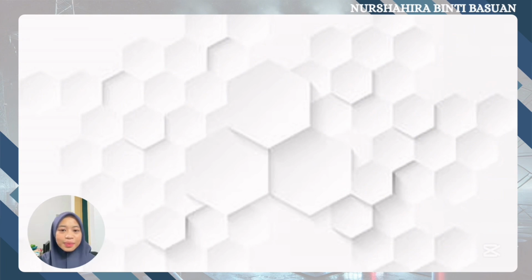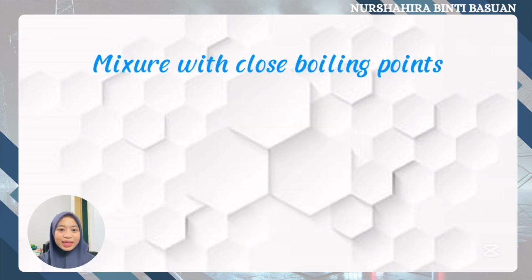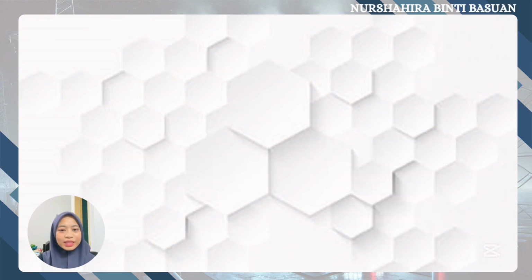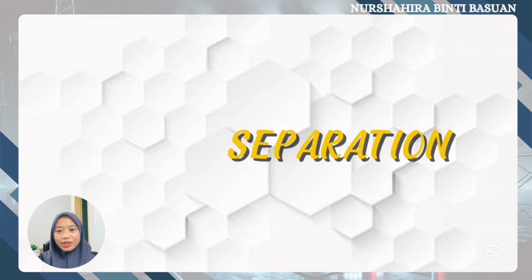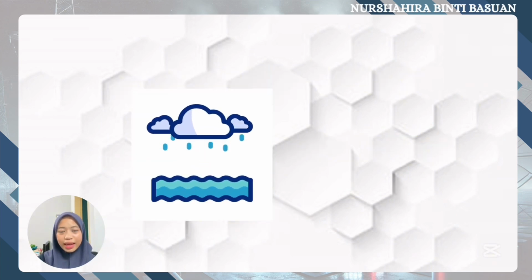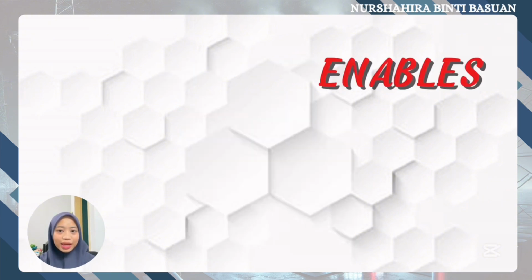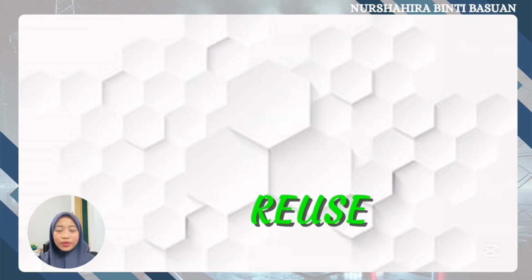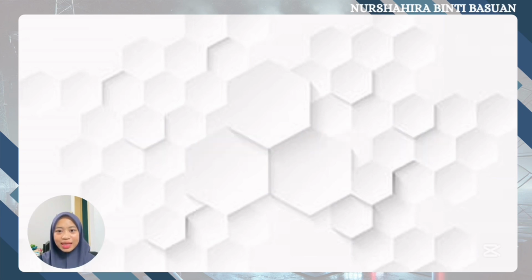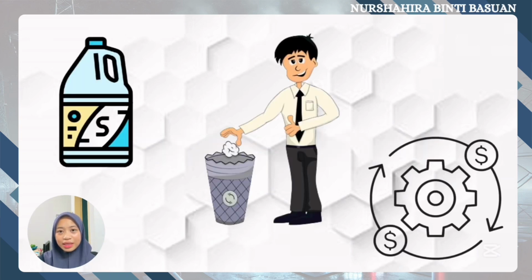Second, precision with fractional distillation. For mixtures with close boiling points, such as ethanol and water, fractional distillation provides precise separation by utilizing repeated cycles of vaporization and condensation. Third, recyclability. Distillation enables the recovery and reuse of valuable liquids, such as solvents, reducing waste and operational costs.